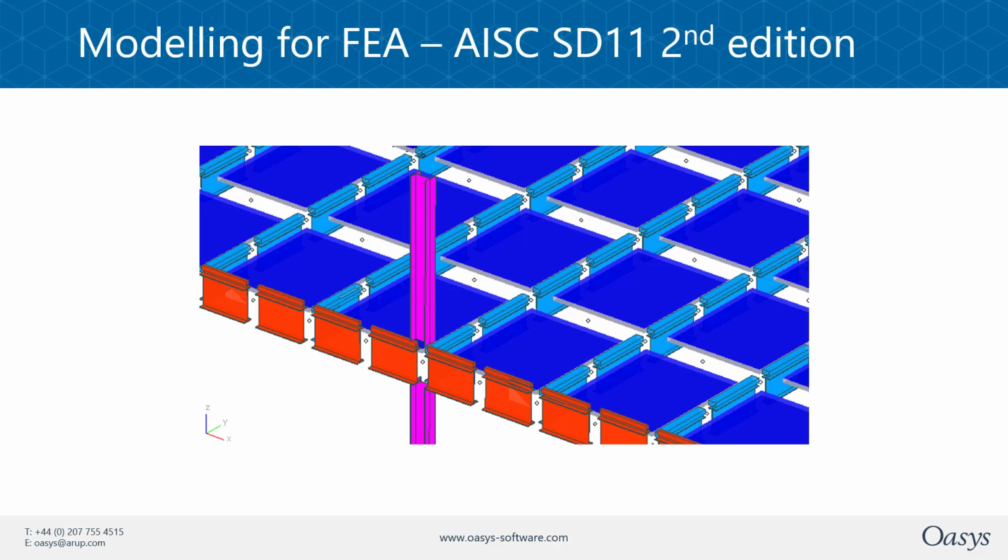Now, unlike the other guides where we would offset the slabs to the beams, the AIC guide recommends you explicitly determine the composite section for each beam. Now, this does allow you greater control over the stiffnesses, such as the increasing stiffness of edge beams and so on, and you don't have to compromise on the neutral axis of where the composite floor is.